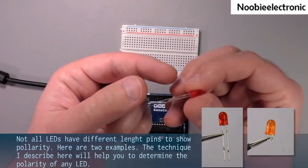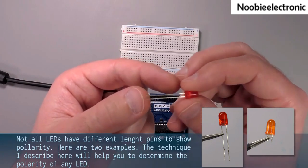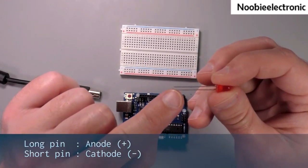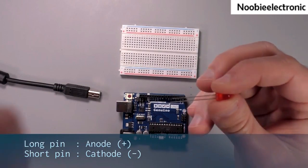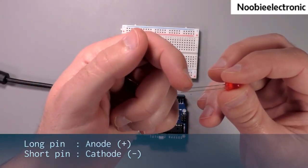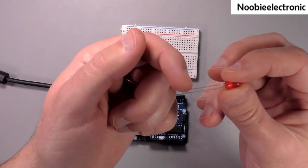So LEDs have to be connected in a particular way to work, and if they are connected in reverse, they won't work. The long pin of the LED is called the anode, and that is the positive side of the LED. And the short pin, the short side of the LED, is the cathode, and that is the negative pin of the LED, the negative side.